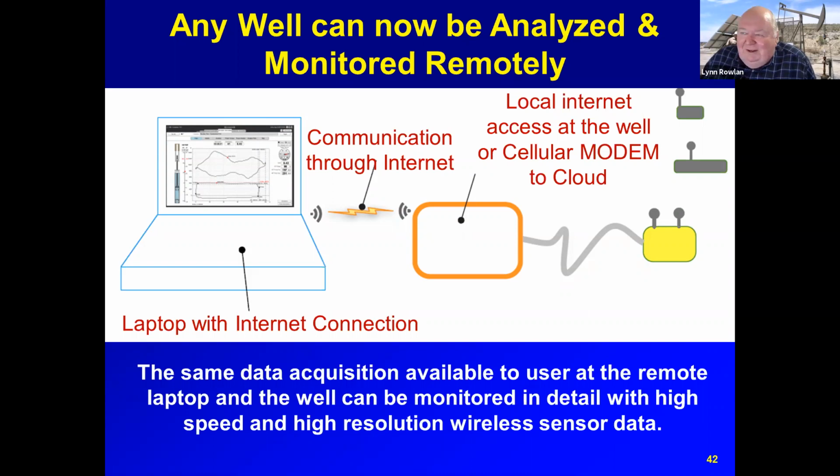If you have a lot of sand, sometimes that limits your ability to use the sucker rod pump. Another thing that limits sucker rod pump use is wellbore deviation and lots of gas. So when you have a really tough problem like that, this sounds terrible, but you may want to consider using gas lift.